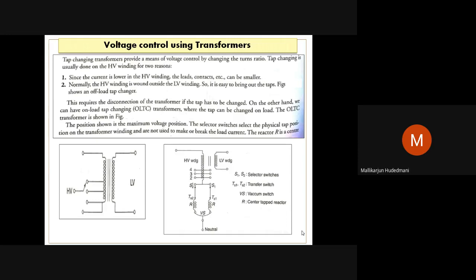And we just initiated how exactly the tap changer functions in the system, that is the OLTC, on-load tap changer. During live service, how the taps are altered to the next and other, depending upon the requirement of supplementing or decreasing the voltage by tap changing. That mechanism is shown symbolically in the right hand side bottom figure.